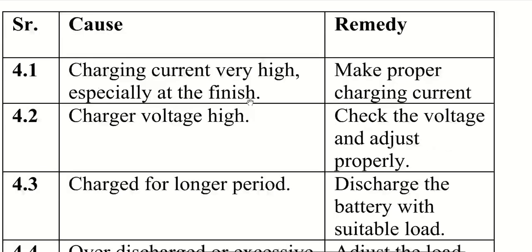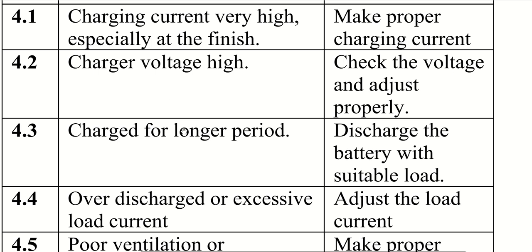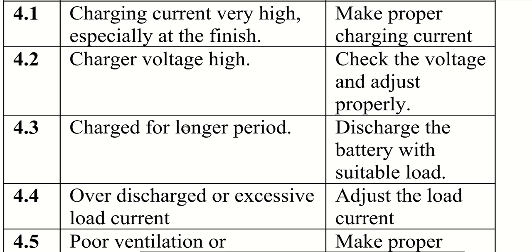Sometimes there is a danger of the battery blasting off, so keep vigilant. If its temperature goes above the specified levels, you have to take care of that. Charging current very high, especially at the finish: make proper charging current. Nowadays you have smart chargers. Charging management is a specific area, and the chargers are very smart nowadays.